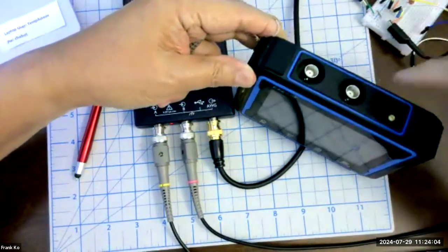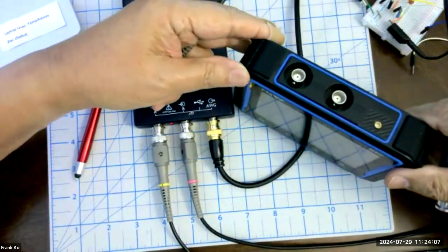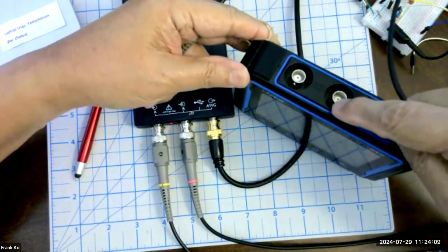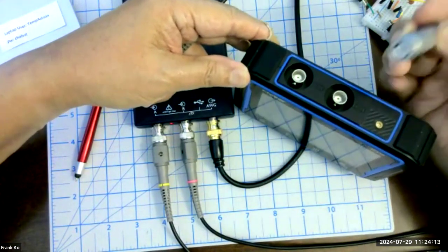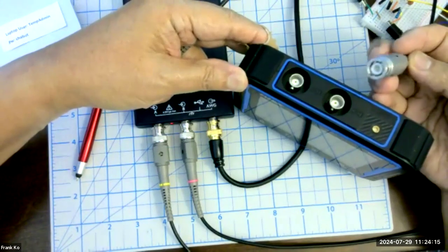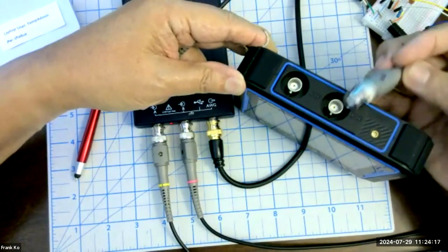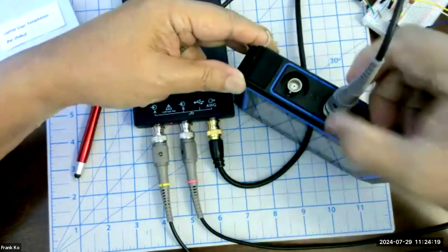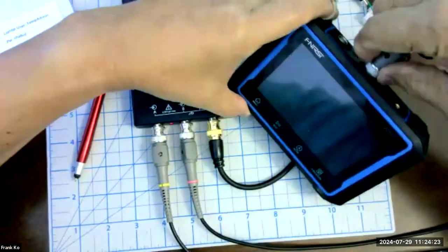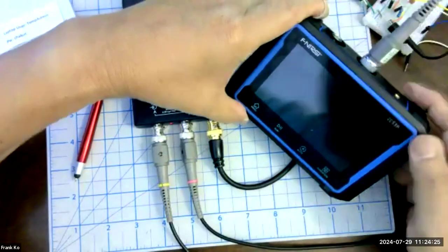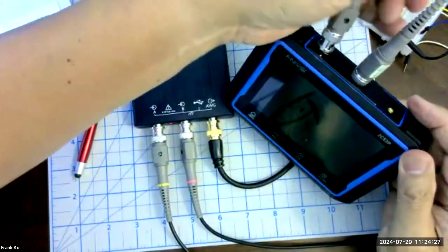Again, line up the pins. You can see the pins, those little shiny tabs on either side, 180 degrees apart on the BNCs. Have to line them up with the slots in the BNC connector. So line them up and push down, and as I'm pushing down, give this a firm push and a twist. It rotates and clicks. And the same thing is true here.